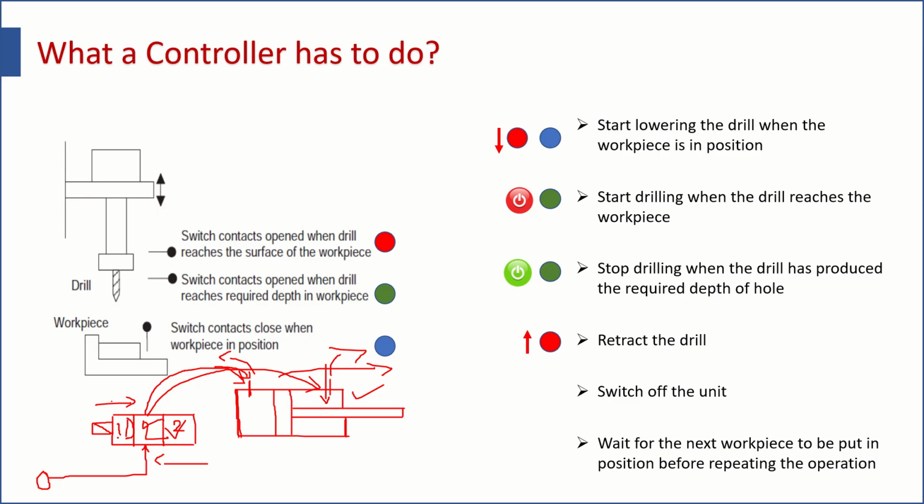When you are using a solenoid valve, then when you energize the valve electrically, it will be moving in this direction or that direction. For that you are giving an electrical signal. So now you are applying an electrical signal in order to control the motion of this cylinder. Therefore this is called an electro-pneumatic arrangement. Now what you are going to do actually, you are going to connect your cylinder here. The piston rod will be connected to the body of the, I should say, motor assembly of the drill machine, and when this cylinder will be coming down, the drill machine will be coming down, and when this cylinder will be going up, this drill machine will be going up. And the DCV, that is the direction control valve, which is actually controlling this pneumatic assembly, is controlled through this switch. Therefore this is called an electro-pneumatic assembly. Am I clear?